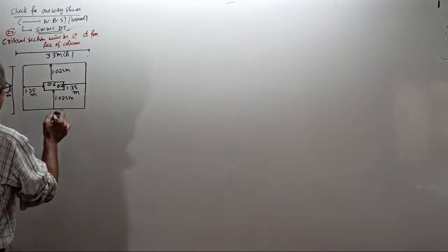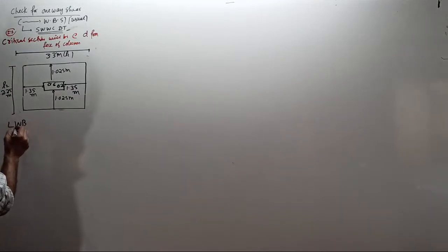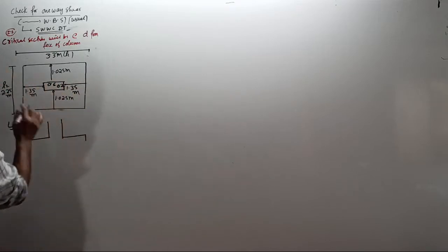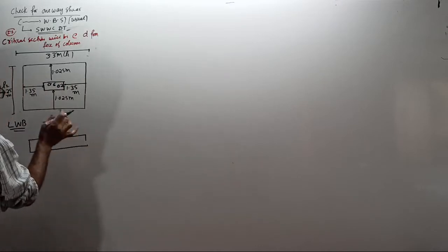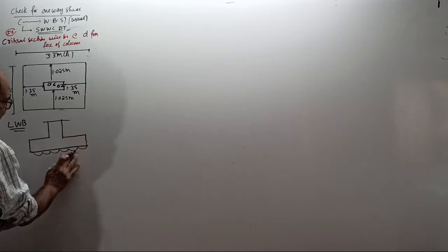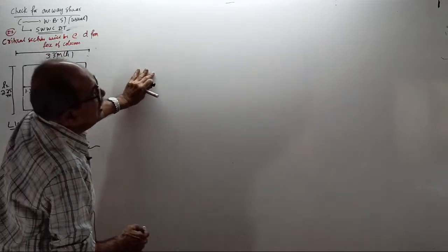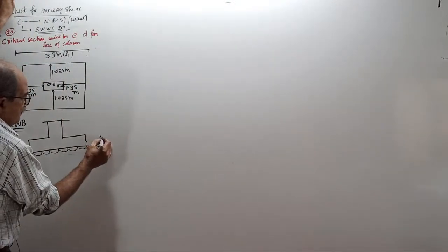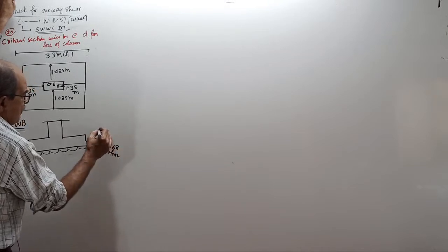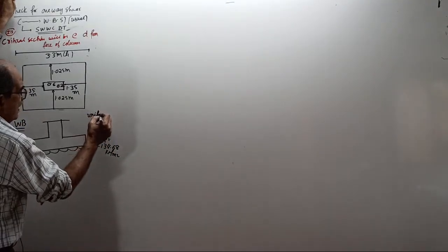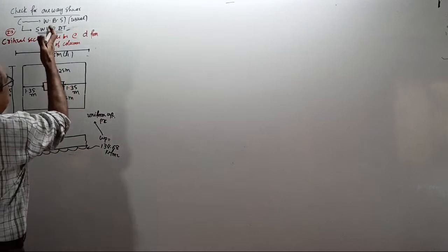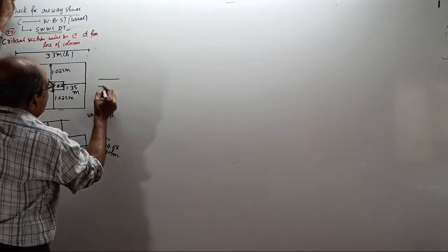Now, consider lengthwise bending. If I put a sketch here, it will come like this. Projection you can see here. I don't have to write once again. This is 600. There is an upward load, I'll put it somewhere here. This upward load is 134.68. It is WP, upward pressure, 134.68 kilonewton per meter square. Remember, it is uniform pressure, very important. Uniform upward pressure, that's why UDL. Then, if I see from this side, what can you see? You can see the smaller side of the column.